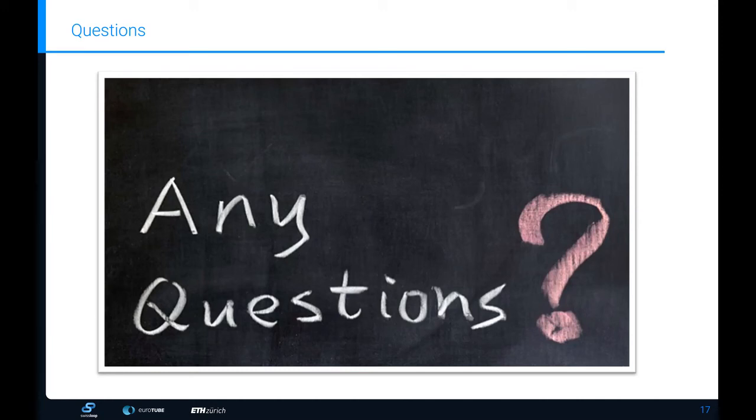Okay, thank you. The next question is, why did you use the state space approach for your thesis and not one of the others? How would the outcome be different with other approaches? I think I chose it for performance reasons. The state space approach is mainly a 0D approach, so with no room dimensions. And because you have no room discretization, it makes your model very fast. That's the main point why I use this kind of approach.